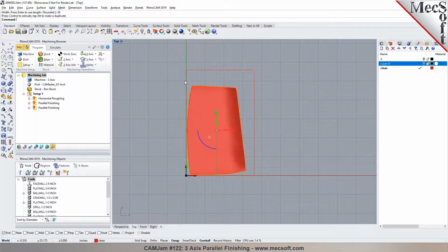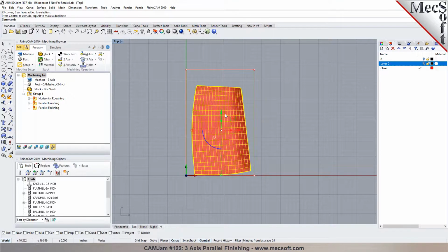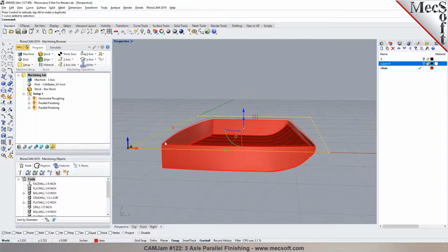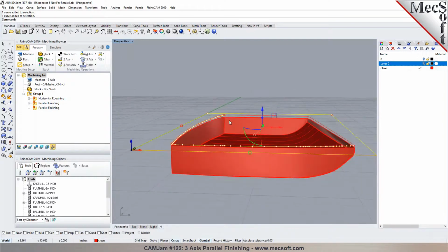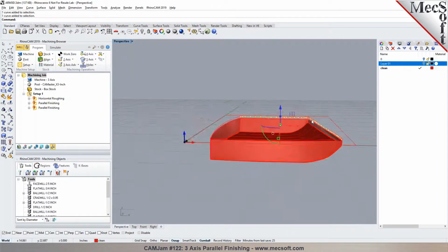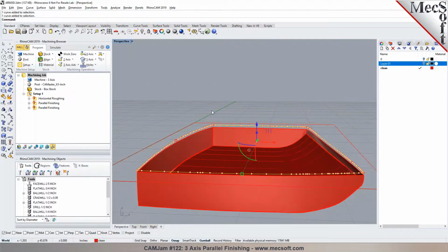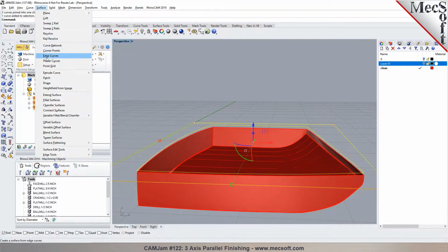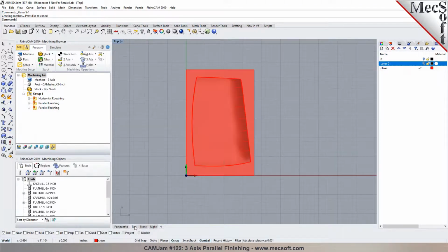So now I can place the part wherever I want it to. I can specify where this needs to go. Like, for example, I'm going to put it right in here. Okay. All right. And so we can basically select these two, and I can cap this. And now I can select this and do a surface using a planar curve. So that puts a plane on it. You see, create a cavity right there.